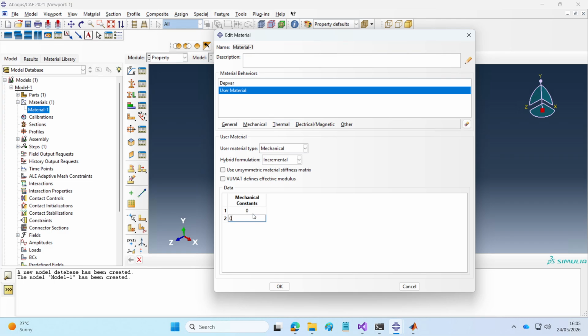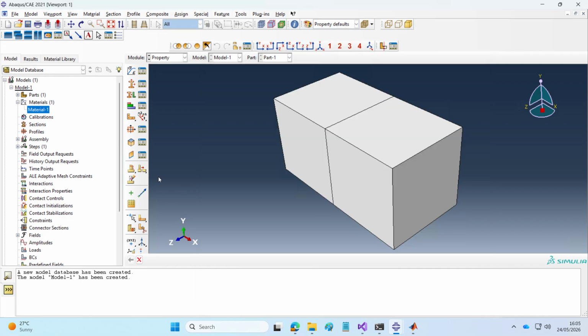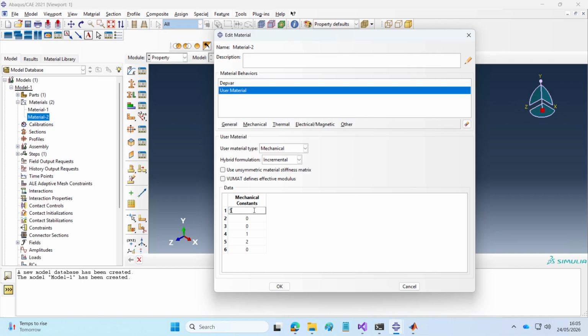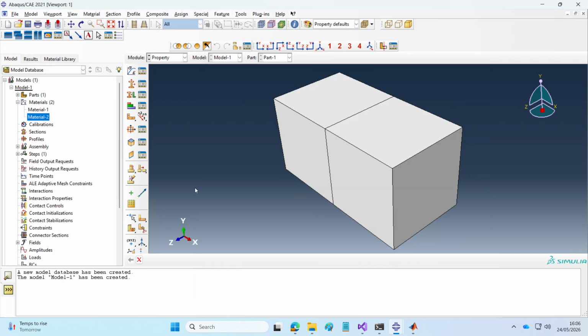Let's put the Euler angles 0, 0, 0, and this is grain number 1. This will use material number 2, and it will use user materials.f. So I think that should be it. Then if we copy this and create another material, we edit that and just change the other angle to 45. That should do it.